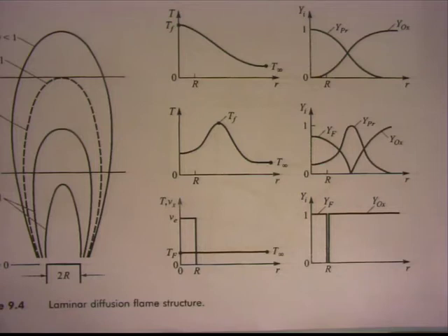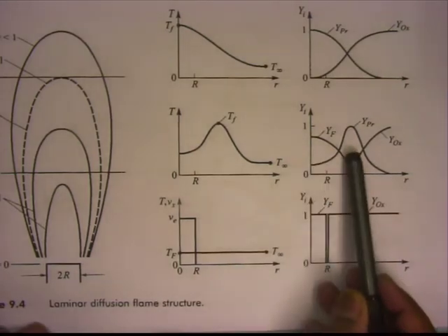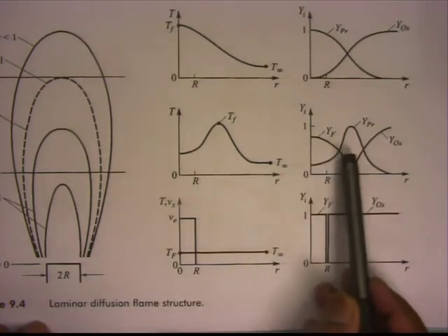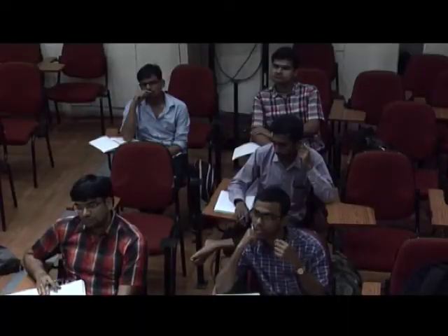Because at high temperature, as we earlier also discussed, temperature will be higher near the flame inside, so oxidizer will tend to diffuse to initiate reaction somewhere near inside the flame. Okay, if I understand you correctly, I think what you were saying is the fuel is moving from the center line towards the flame, but as it moves towards the flame, because of high temperature, some of the fuel will break down. Is that what you're saying? Some of the fuel might tend to initiate reaction with the oxidizer, so oxidizer will also diffuse.